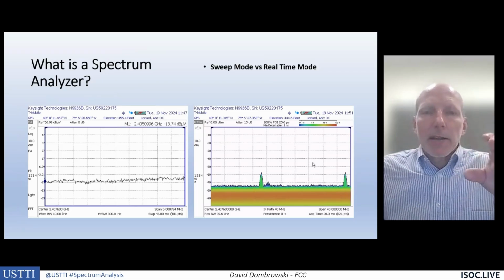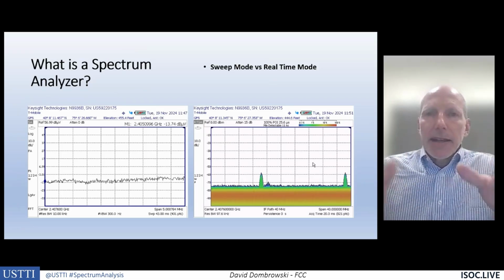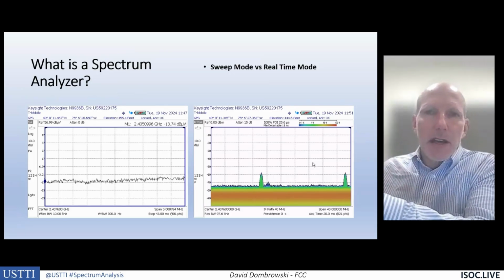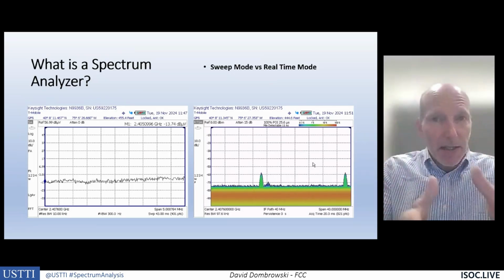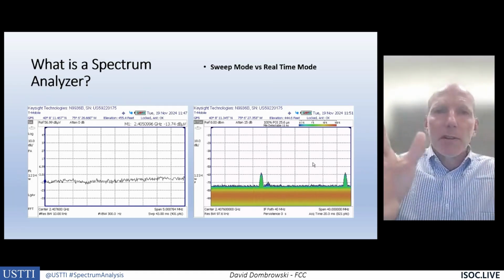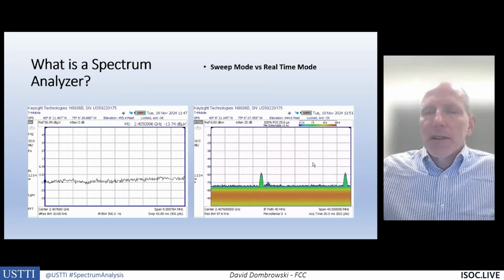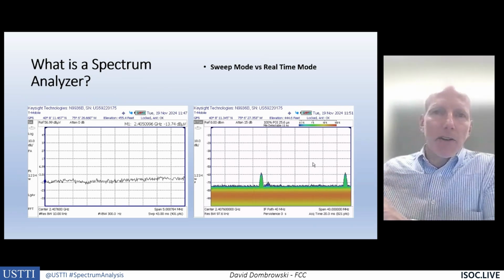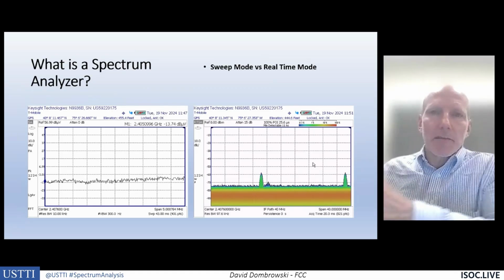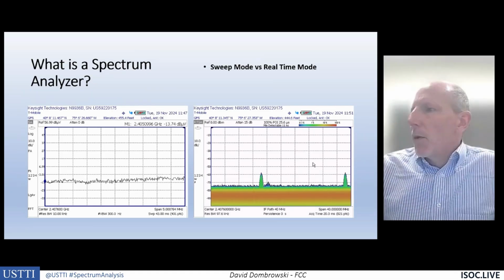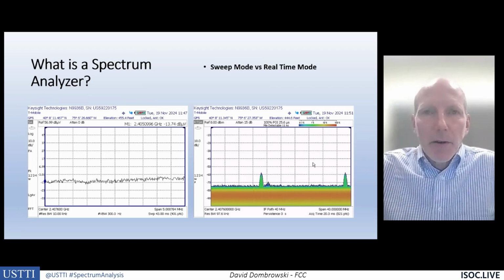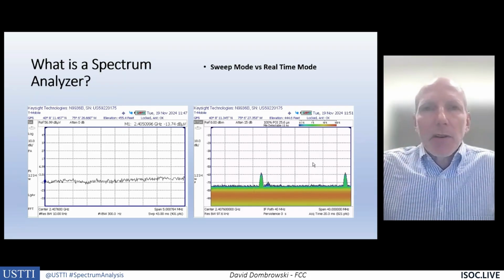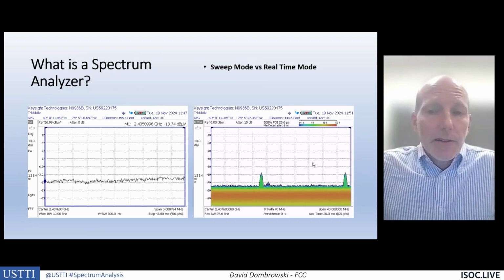You can also downconvert signals. You can buy a device called a downconverter, and it takes the spectrum that is on high frequencies and transposes it, by that superheterodyne mixing, down to a lower frequency. If I'm band limited, my analyzer only goes up to 14 gigahertz. I could take the spectrum that's maybe at 100 gigahertz, transpose it down to somewhere that my spectrum analyzer can receive, and I can observe it. And so you can also do it by frequency transposing, by buying devices that connect between your antenna and the analyzer. Does that answer the question?